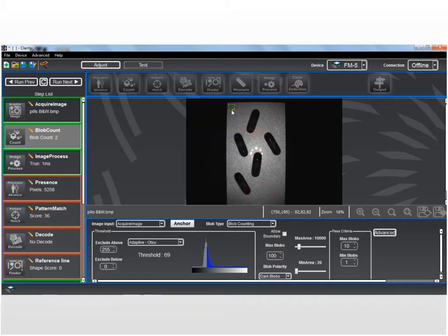Well, just like with the other plugins, I get my region of interest. I'm going to set that up around the area in the image where the objects are that I want to recognize. You see right away I get all this little noise pops up where the algorithm is detecting just slight illumination variations in the image. I can change some of that. I'm going to go to an adaptive background threshold, where now the threshold used sort of adapts across the image for those lighting variations. But I still get a couple of them in here, as you can see.